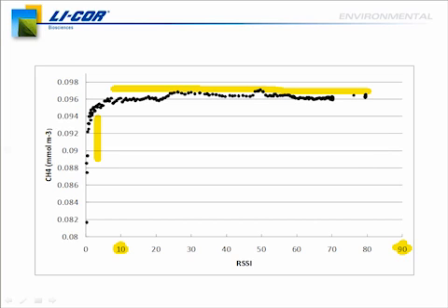But just as a point of reference, we did operate the instrument, as I said, in a pollinating corn condition here in Nebraska for a while, and we were able to only have to run the washer maybe every few hours. So it doesn't happen too regularly, but it will depend on the site. And then the second part of that question ties in well. How often do you have to fill the reservoir? The reservoir that I showed you has a 4-liter capacity, and if you run your cleaning cycles for about 20 or 30 seconds at a time, that reservoir will give you about 20 or 30 cleaning cycles.